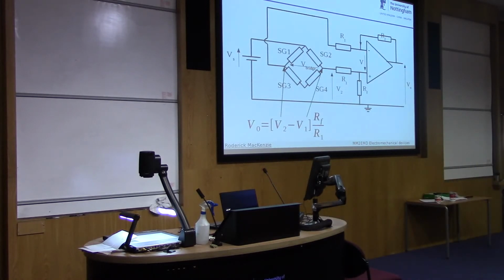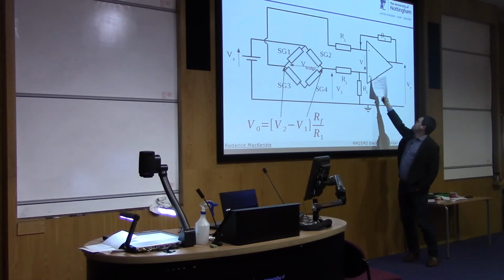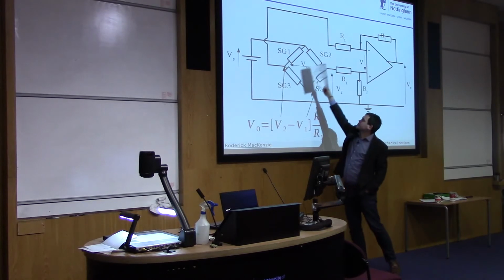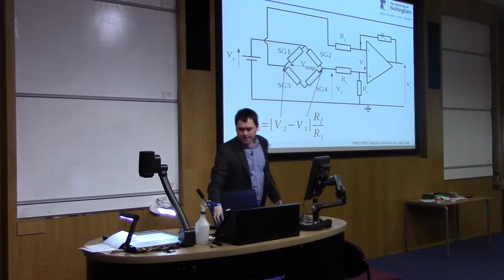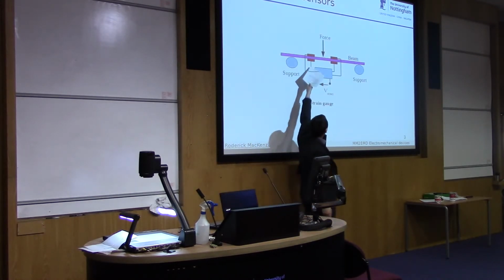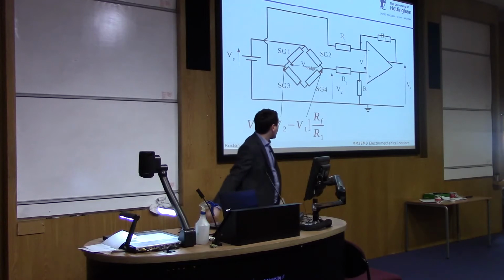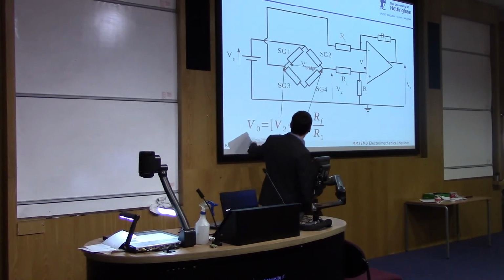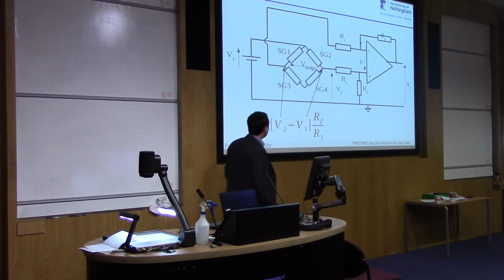But if you do the analysis, here's our op-amp. So let's just look at what we know. Non-inverting input, inverting input, output. Here's our strain gauges. So we've got four resistors, 1, 2, 3, 4, representing our strain gauge, and those are basically on the top and bottom of two parts in the beam to make our bridge. And Arthur derived for you in the last lecture on op-amps this equation that basically says the voltage difference here minus the voltage difference here equals the output here over RF over R1.